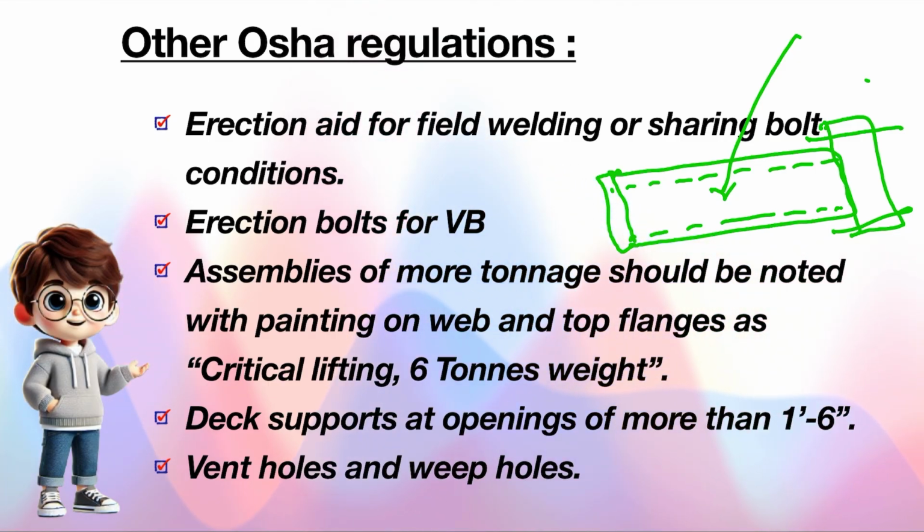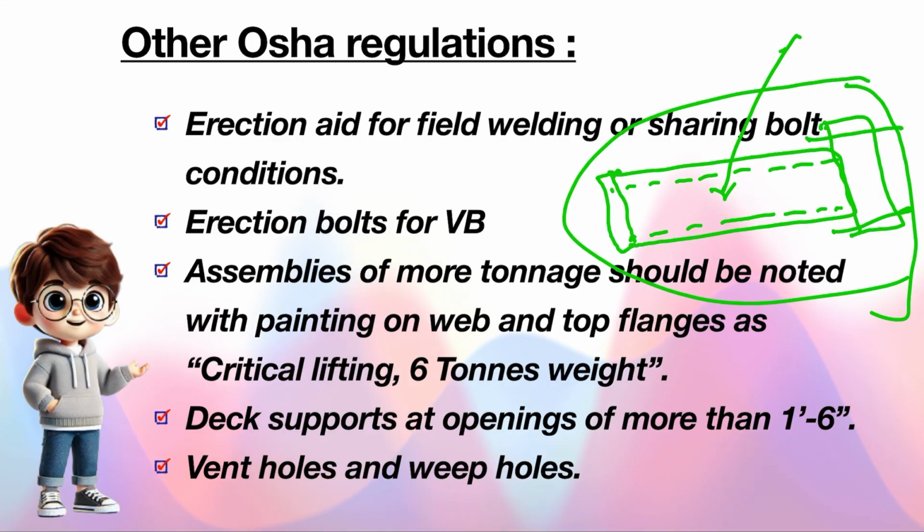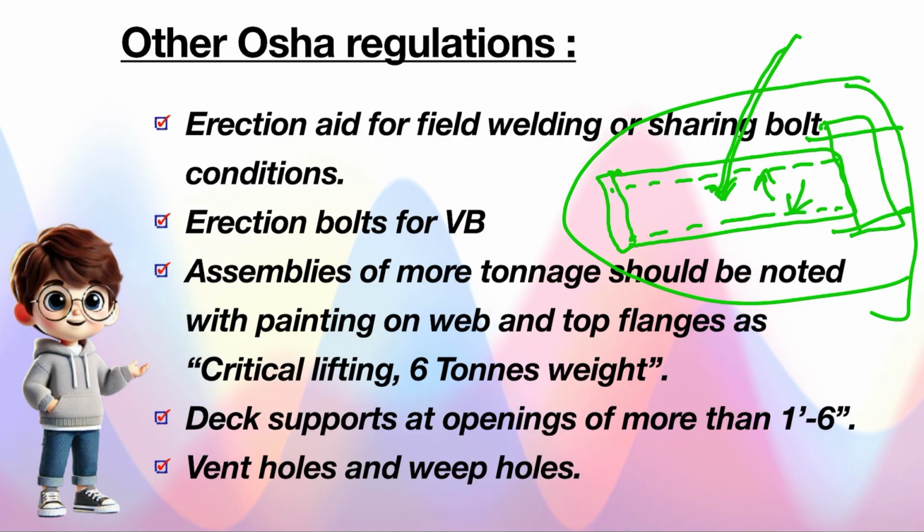If you dip the HSS like this into the galvanization tub, the inside air will build more pressure on the walls of the HSS, and it can cause blasts also, meaning exploding the assembly.